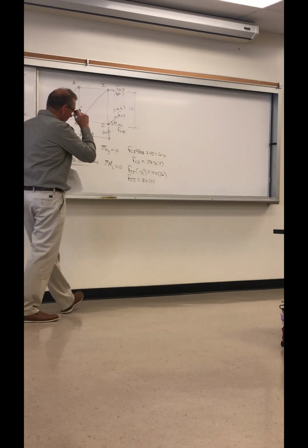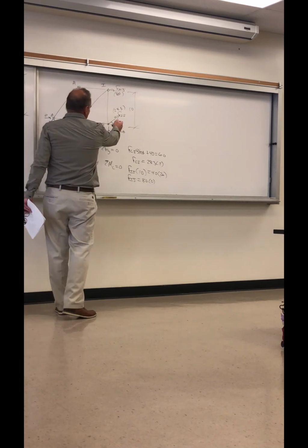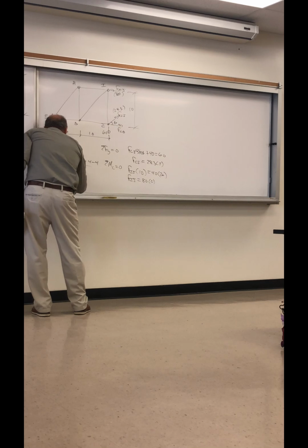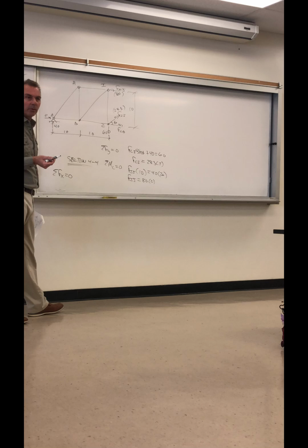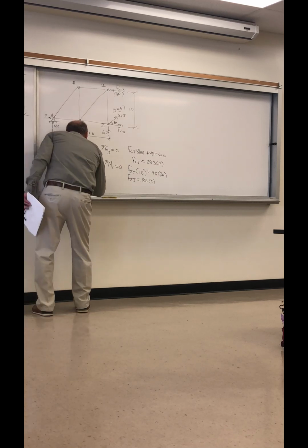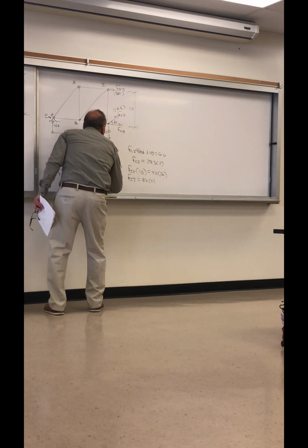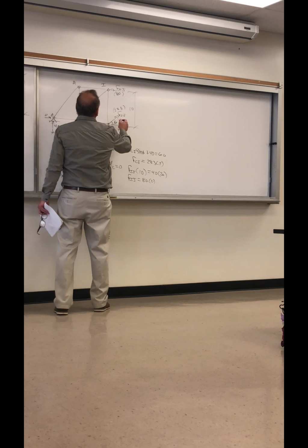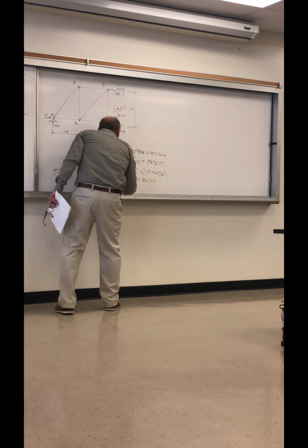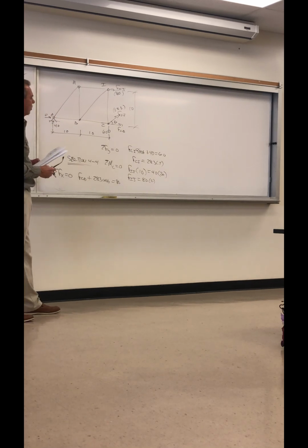And now you have to be careful when you sum forces in the x, because there are two forces there. So we have summation of forces in x is 0. F of CD is what I'm looking for, is the third. Remember, it's F of CD plus this 28.3, that same direction, times the cosine of theta, equals 80. So we needed to include the horizontal component.